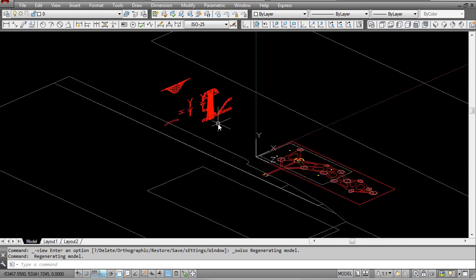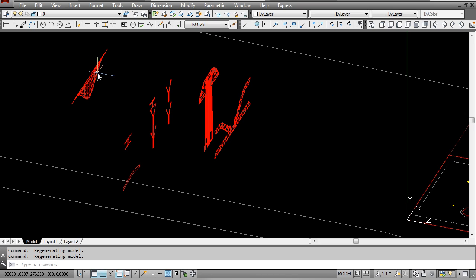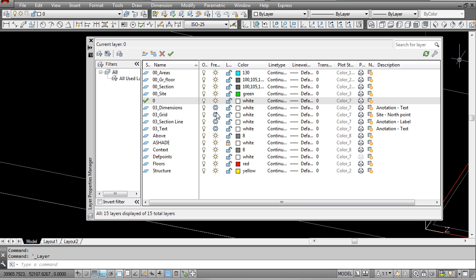First, just to make it editable individually, I'm going to give each one of these objects a different layer, and that's going to make it easy for me to use the layer isolate tool to select one of them, isolate it, and work on it individually without having the fuss of trying to work around too many objects as the density of our section starts to increase. So I'm going to open my layer manager and create about 4 or 5 or 6 new layers, and assign each of those individual objects onto those layers. While I do this process, which is quite simple, I'm going to be pausing the video so you don't have to re-watch me do the layers, and I'm going to come back once those objects have been relayered.